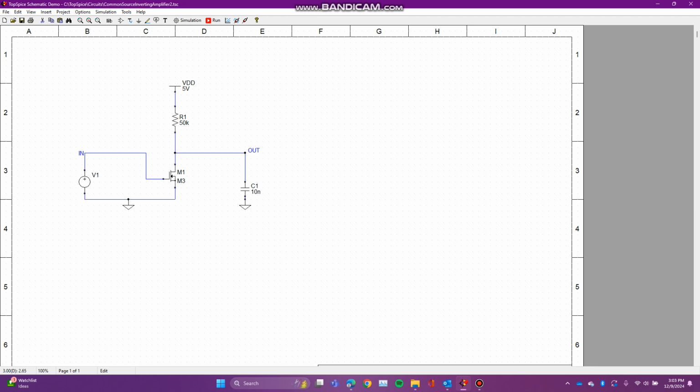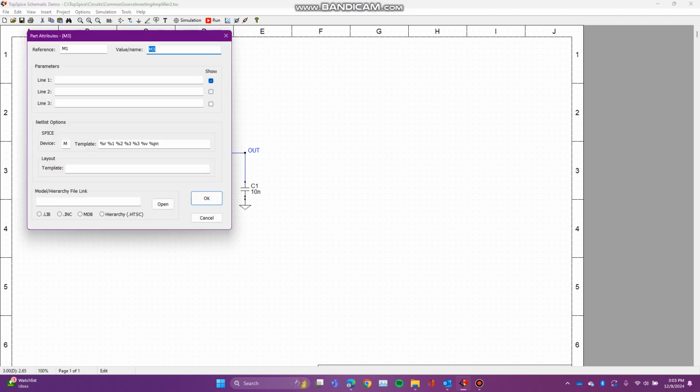And then now we need to be able to set the transconductance parameter of the MOSFET, and we're going to do that by setting 3 values to transconductance and 1 value for the turn-on voltage. Right now we're setting the length and width of the gate of the MOSFET.